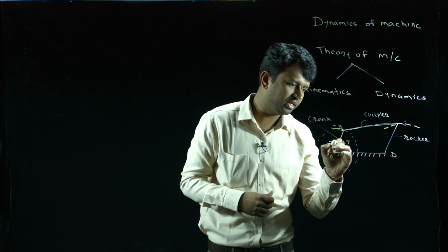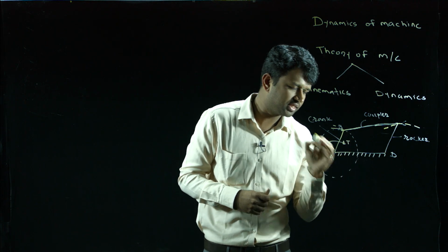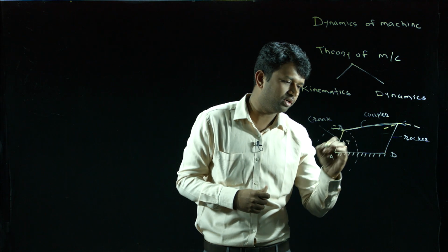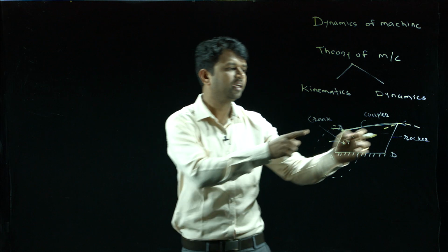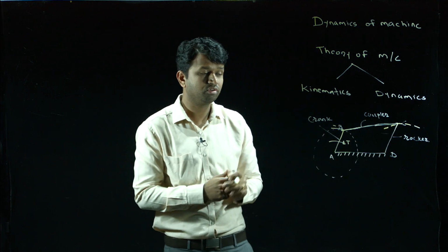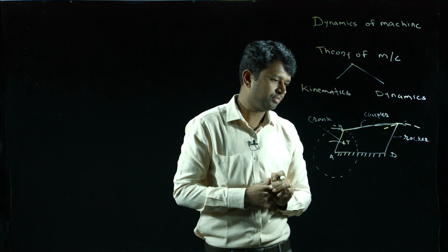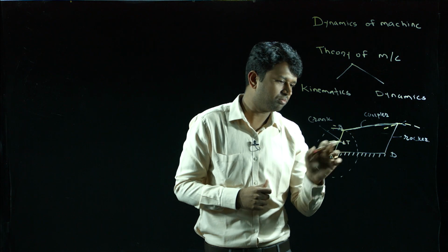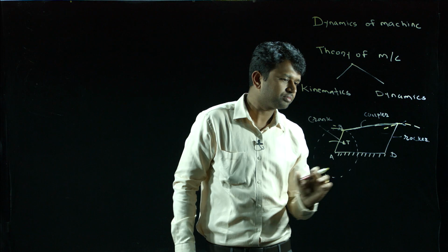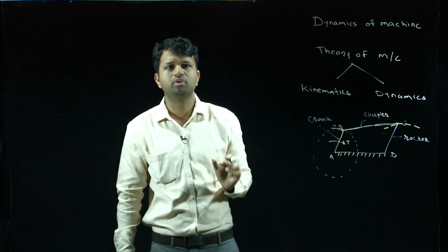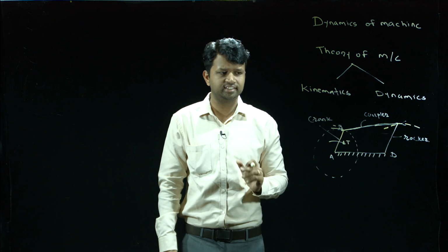Suppose the torque is acting on this crank, okay. Due to that torque, the force is acting on this coupler, and now we are interested in designing this coupler. So first of all, we will calculate the force, okay. That force we can calculate from the torque. Then from that force we can calculate the stress.